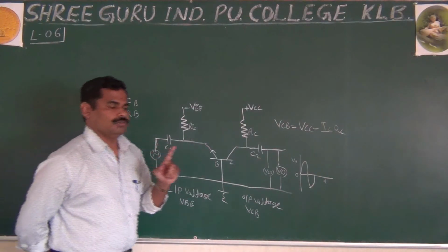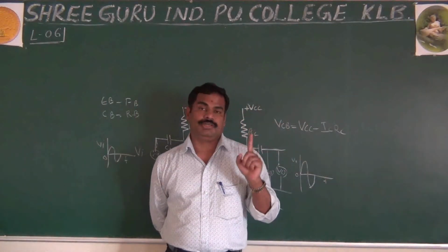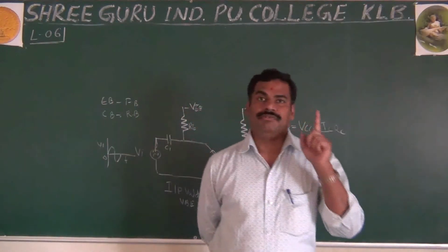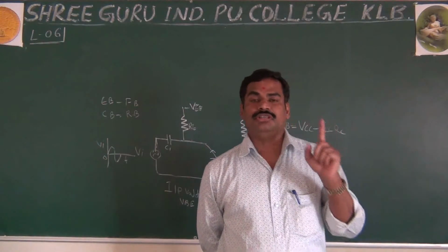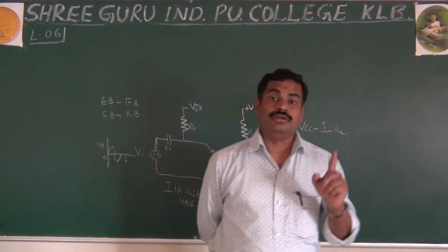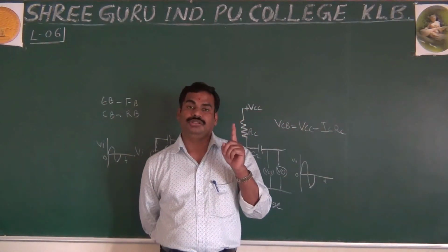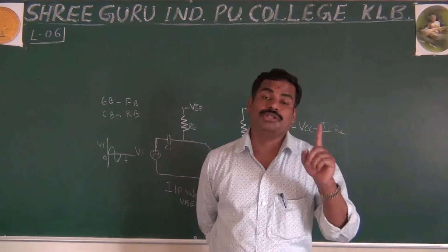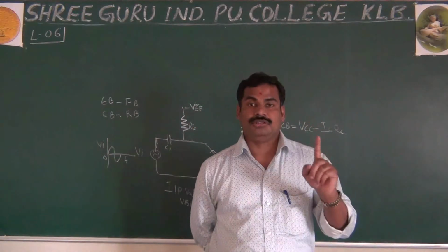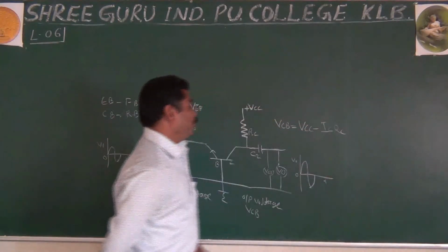The most important thing, we want faithful amplification. Always we want faithful amplification. As I said in the beginning, faithful amplification is nothing but increasing the strength of the signal. It may be current or voltage. The important thing is that without changing the frequency or the shape of the signal, you are only increasing the amplitude of the signal. That is the faithful amplification.